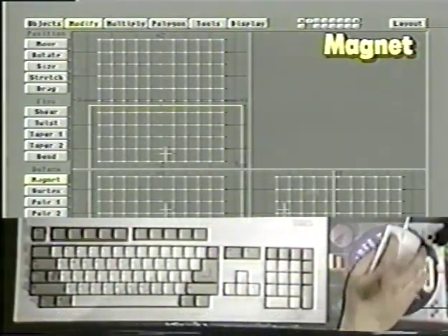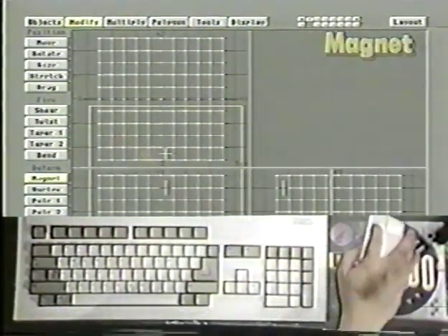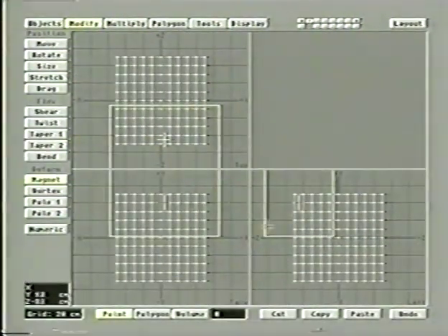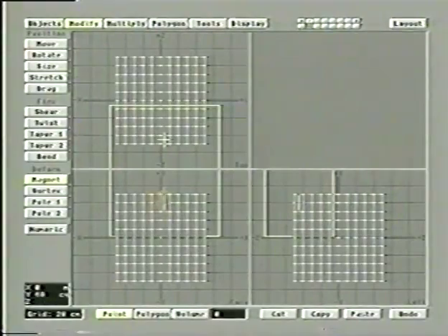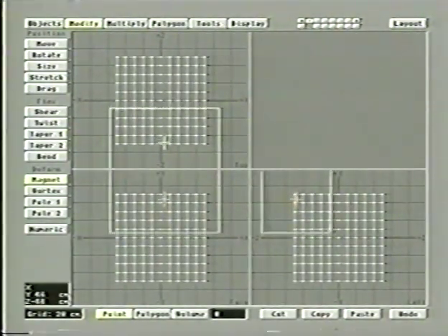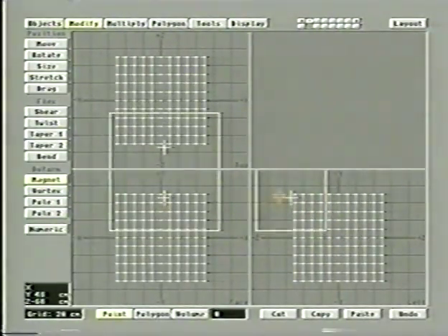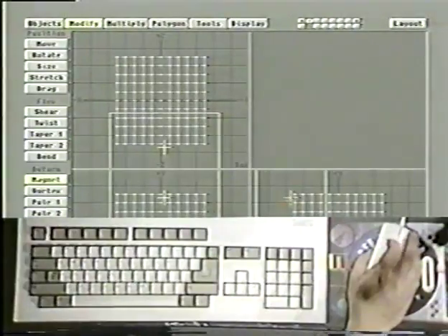And what I'm going to do is I'm just going to focus on this upper corner here. So notice we've got one corner chosen. This is with the left mouse button. Now, this center here, where this line is, this shows sort of, again, it's called magnet for a reason. We can click on this and drag it around, by the way. But the way this works is that polygons that are closer to that center will be affected more by the magnet tool.